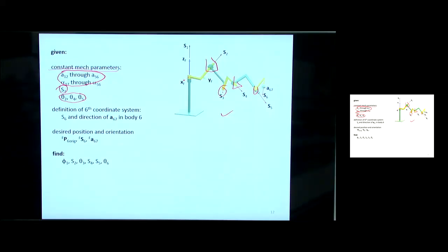And then you say, well, yeah, there's a revolute here. How come I don't have an S1? And it's because that's, remember, the first joint where we go relative to that fixed coordinate system. There is no S1. And again, the S6 is not exactly a constant that never changes. It's a user choice to establish that last coordinate system. So for our problem statement, that's the stuff that we know that never changes.